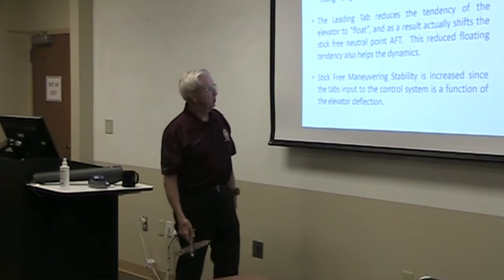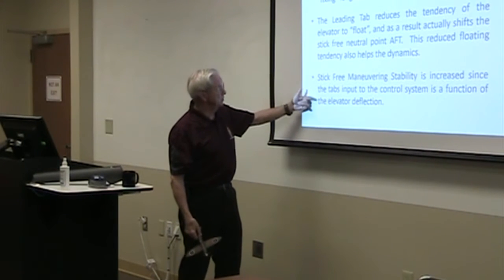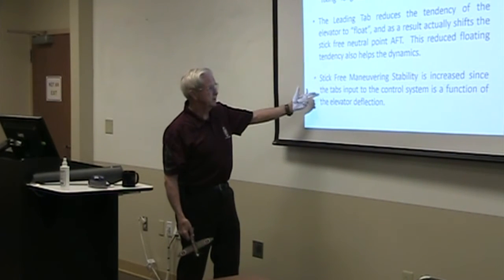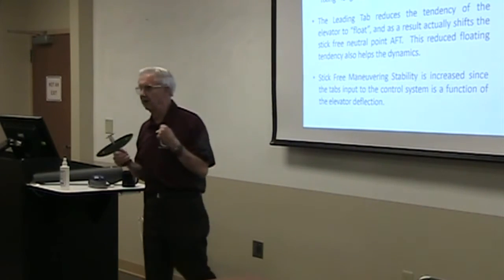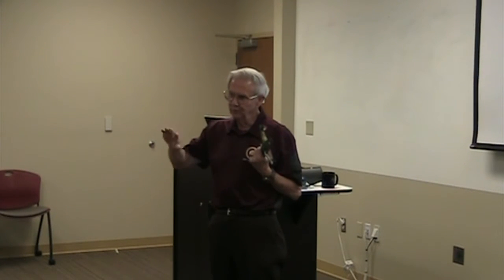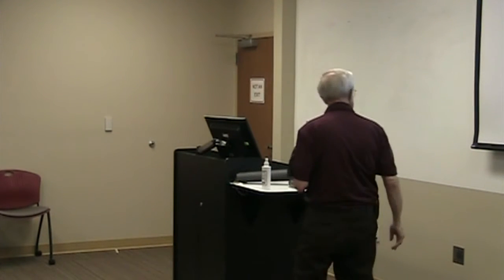So, stick-free maneuvering stability is increased with this leading tab, since the tab input to the control system is a function of the elevator deflection. And what happened in maneuvering? We had more deflection, right? Due to the rotation, we had to have more deflection to get the additional G.